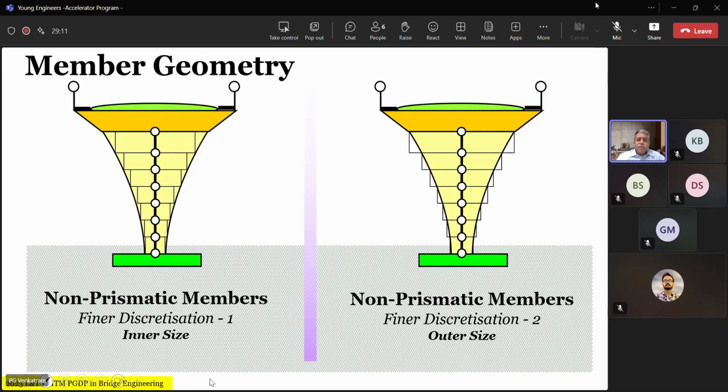Now, let us say I have another way: I don't use the self-weight option of an analysis software. I put the exact self-weight as I calculate. That can be overcome. You agree? Self-weight is a problem only if you use the internal self-weight calculating mechanism. Okay. Now, if I were to say the choice of the model depends upon what is in your judgment the governing stress resultant, and the governing load condition,